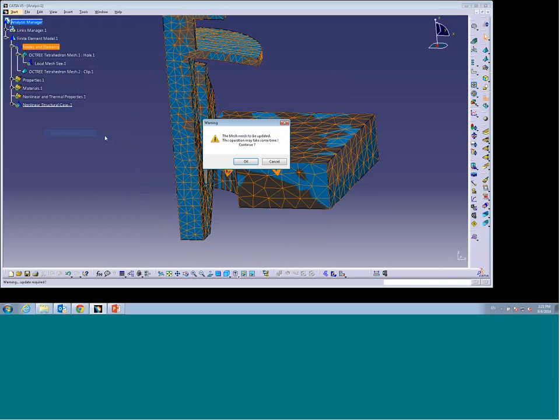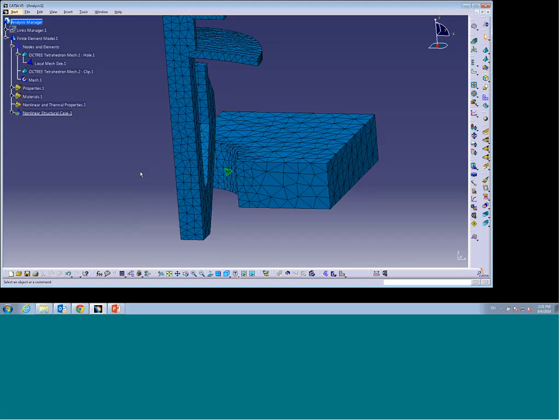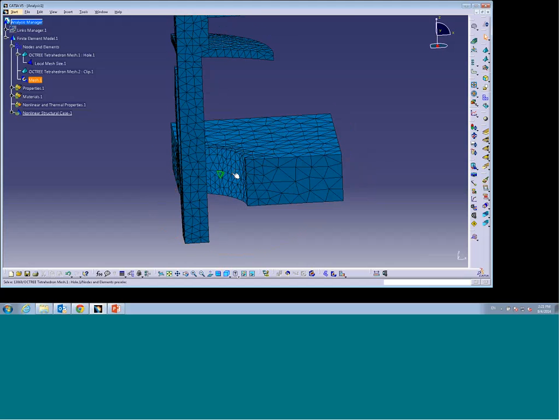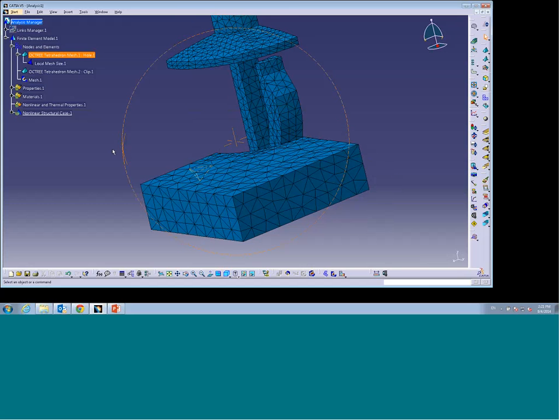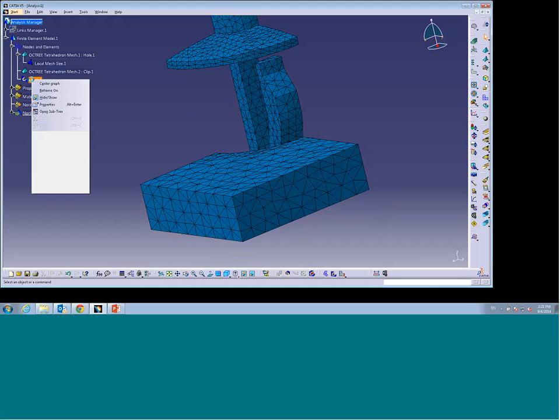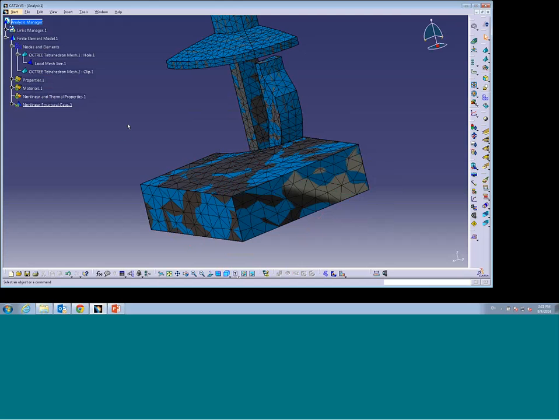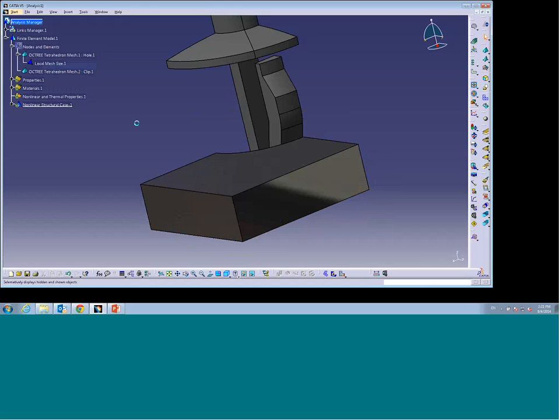and I'll do mesh visualization. Okay, so as you see on the curved surface, on the whole surface in the cylinder, the mesh density is now the same as on the clip surface. Okay, fair enough. What's next? Well, here's what I'm thinking. Again, for efficiency, here's what you might want to consider. Let me clean up the model, okay, and I'll hide nodes and elements.